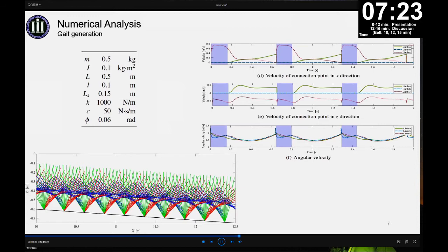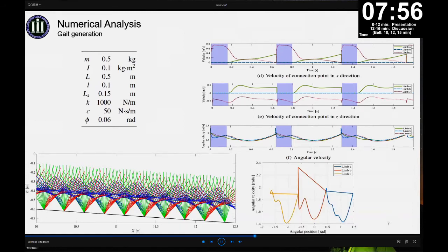Here, a successful passive dynamic walking gait can be achieved if two principles are obeyed. First, from double limb support to single limb support, the vertical ground reaction force of the rear limb decreases to 0, while the front one remains positive. Second, from single limb support to collision, the vertical ground reaction force keeps positive, and the kinetic energy enables the center of mass to overcome the potential barriers.